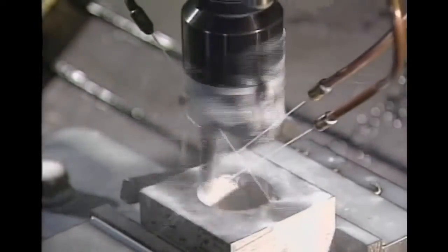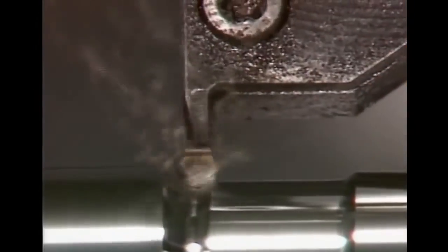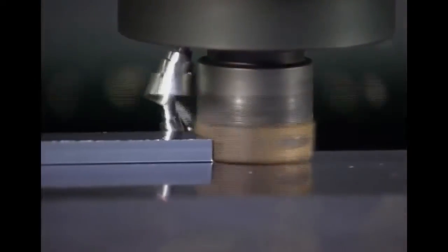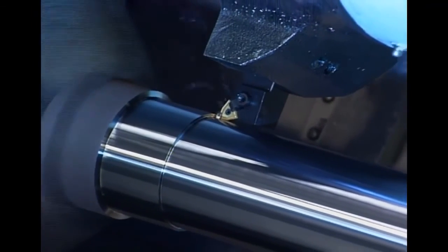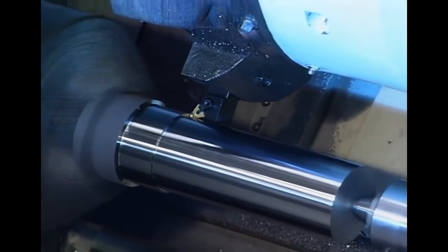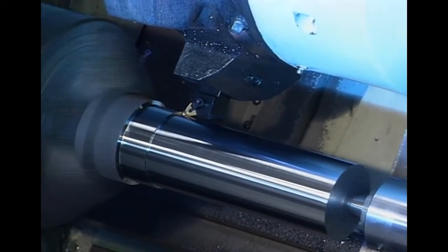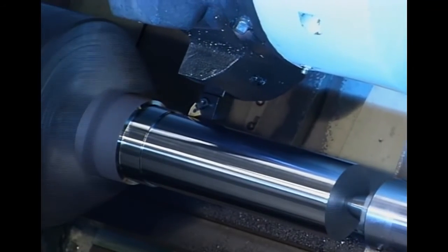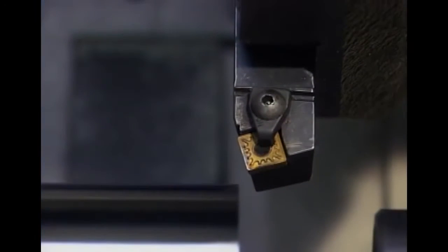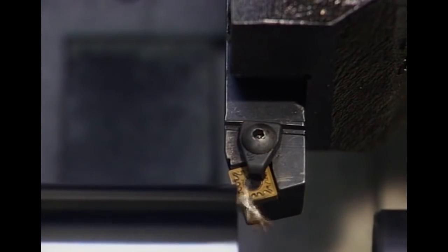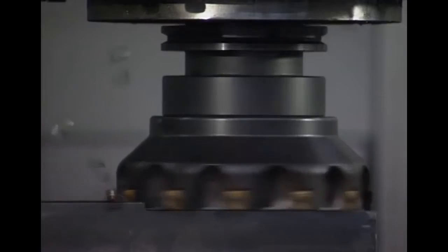Cutting tools cut with an edge, and those edges can be described by their geometry. For metal cutting efficiency, it is critical to select the edge that cuts best, given the material and cutting conditions. The purpose of the edge and its geometry is to create a chip. The right geometry creates chips cleanly and efficiently. The wrong geometry may not cut at all, or cut poorly, fail prematurely, or damage the workpiece surface. Cutting tools fall into 2 broad classes: single point and multi-point tools.